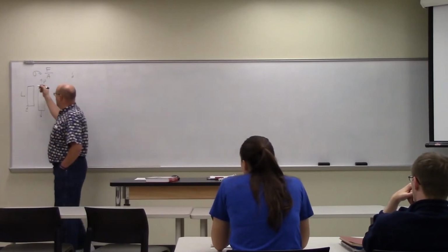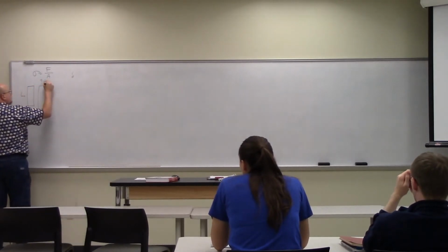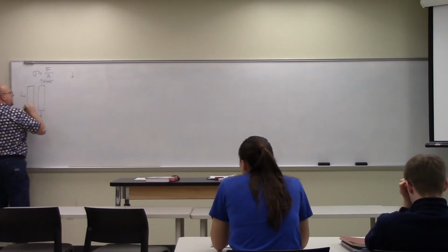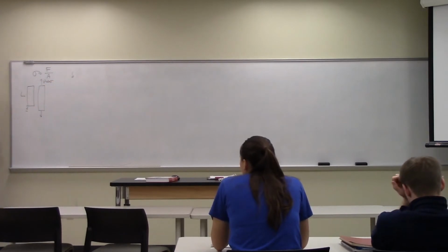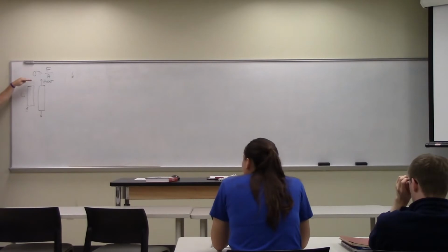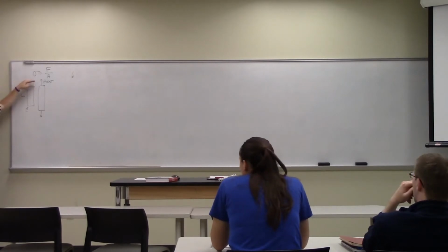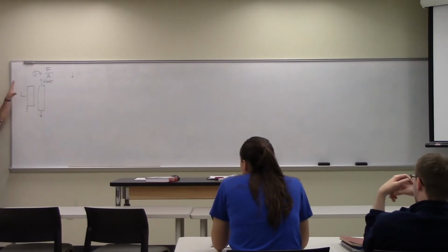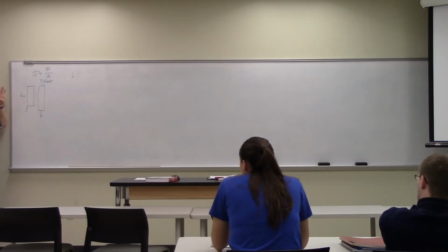So in area, we converted this to a stress by compensating for the area. So now if I have doubled the area, I have to double the load to get the same stress, right? So the point is, if stress is fixed, because area is compensated for already in stress, then what other geometric features are going to change the strain?